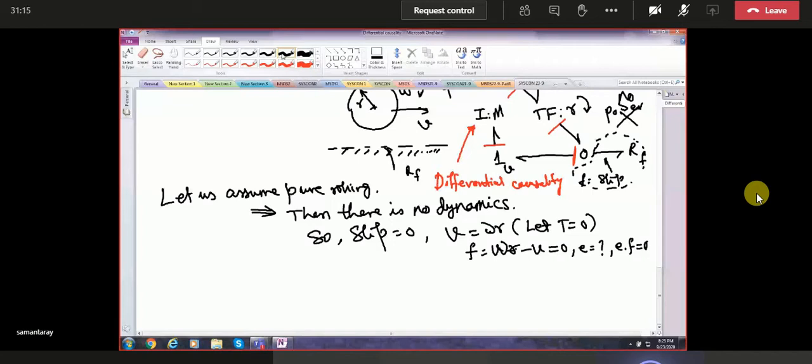If we had given this one integral causality, then that omega I appearing at omega will come in differential causality. So either V or omega, one of them you can choose as independent coordinate. The other one is the dependent coordinate. Whatever is dependent comes under differential causality. So I can reduce this model now. This resistance is gone. This zero junction, we can remove it. So we will just reduce and rewrite that model.